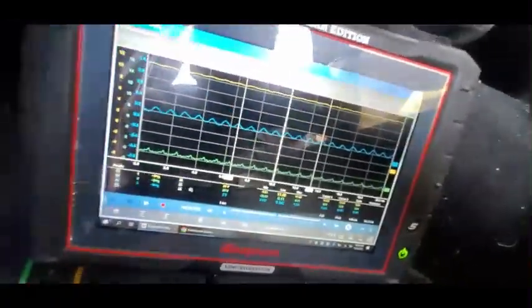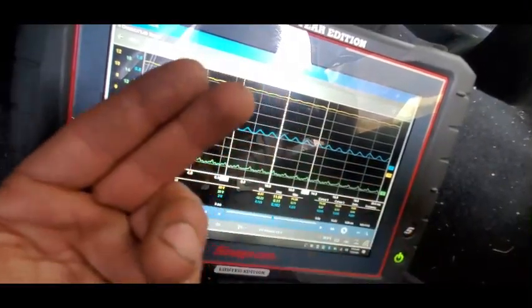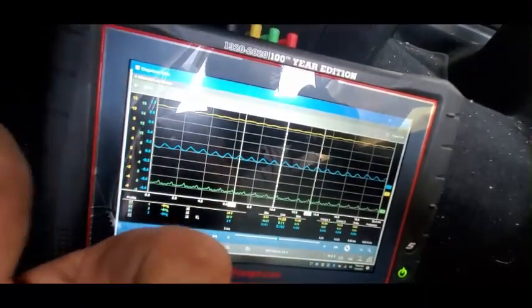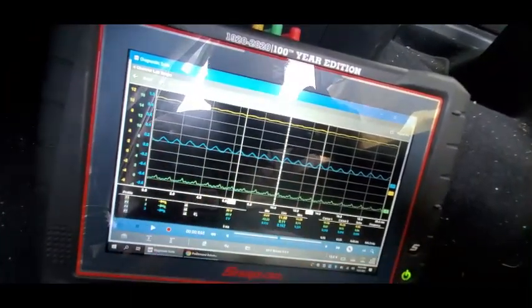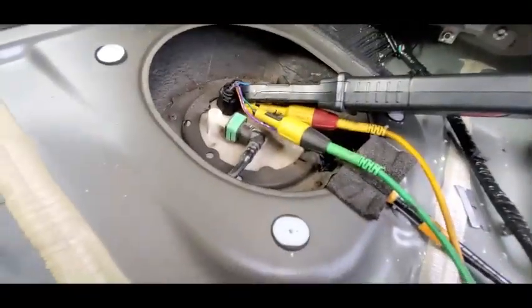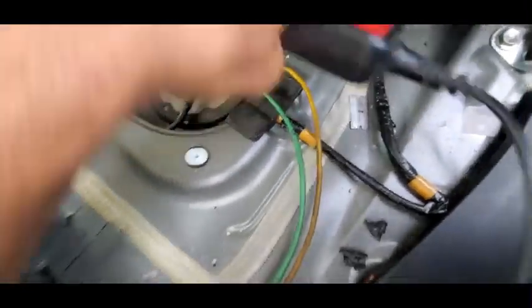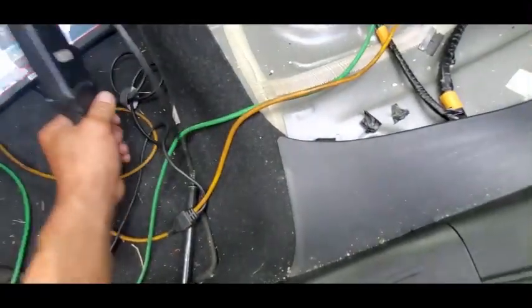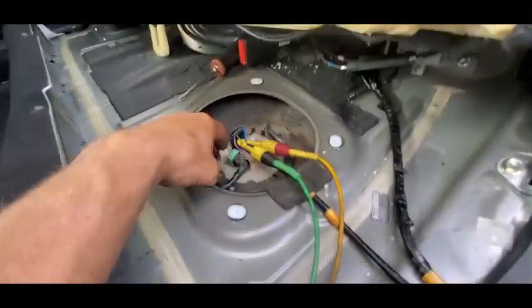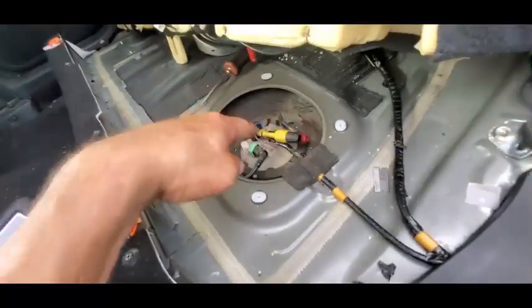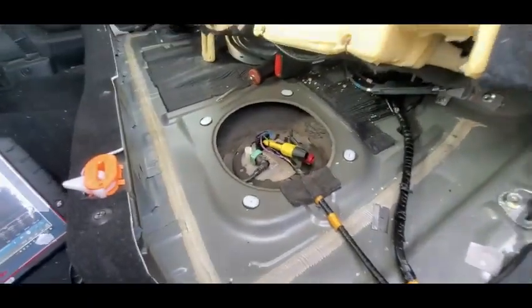I'll just leave this on here and we'll get a pump here. Okay. Do we check fuel pressure? I mean, what's the point? Obviously it's not pushing any fuel pressure. It's only pulling 2 amps. I don't doubt my fuel pressure sensor at all. This is 100% a bad pump. And you can hear it and it sounds weak. And given they only have 18% in their fuel tank, I imagine this thing's been ran low a few times. Not accusing, just saying. And this pump's probably been burned up. So we're gonna leave these piercing probes on here. Obviously we'll have to clean this up and we'll put the pump in and then we'll get after captures, okay?